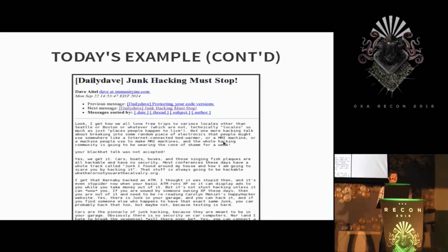And since you can execute firmware on the chip, you can do real-time operations like real-time selective jamming or real-time channel hopping to follow a channel hopping transmitter without having to deal with and compensate for USB latency. And of course, finally, it's interesting because it exists. A binary out there that's in a custom instruction set is sort of reverser bait. So as part of this project, I created a disassembler for the ADF 7242 and the similar families, and I'll post it later for anyone that wants it, if there is anyone.